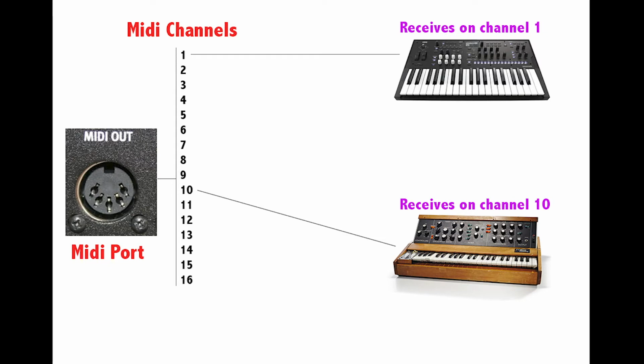So you need to be aware of MIDI channels. Out of each physical port, there are 16 channels. And whatever channel you're sending out on, the instrument that you're sending to needs to receive on that same channel or it will not work. So you need to find out where the setting is for this on your synth or your computer to make sure you know what channel you're actually on, so that's not a problem.